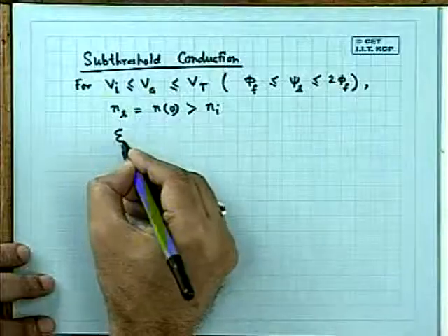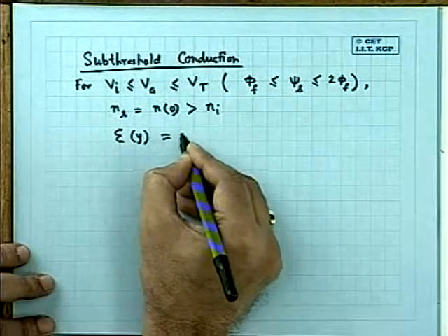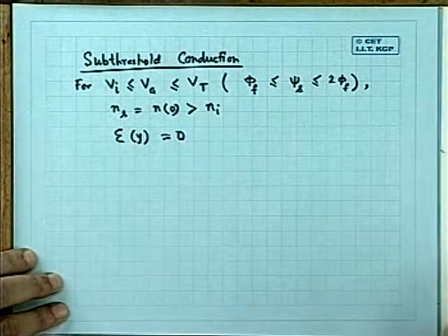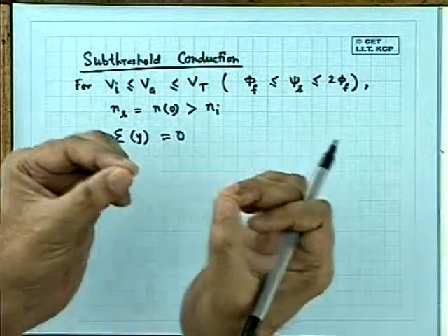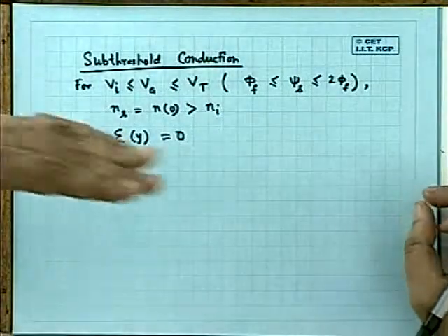So you are sometimes tempted to use these devices even near threshold or subthreshold region. It's very important for you. And then I must understand how the conduction physically takes place in the subthreshold region. In the subthreshold region, you see that Ey can be considered to be 0, because practically there are negligible number of electrons, the current flow is so small that the potential drop in the channel can be neglected. And if there is no potential drop, the potential gradient will be 0.